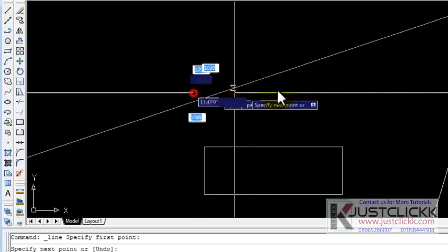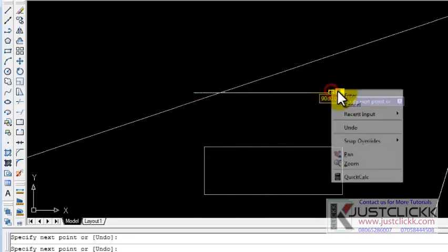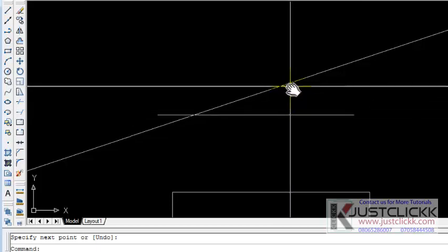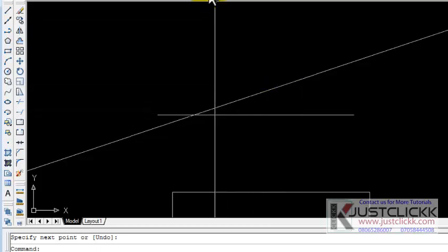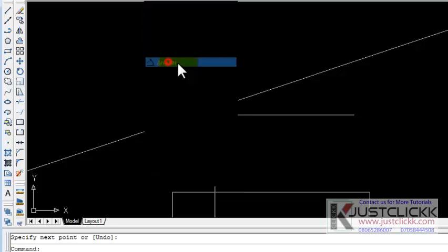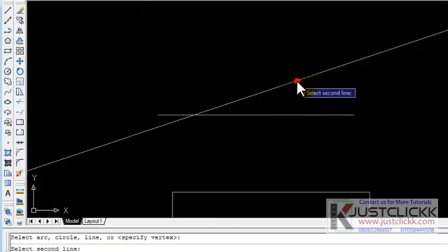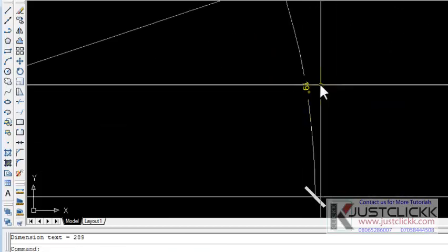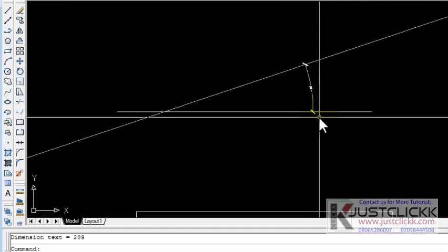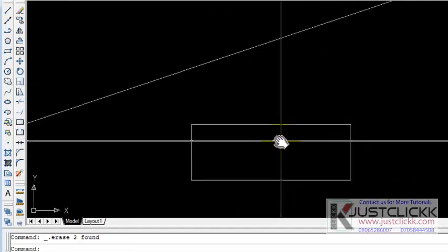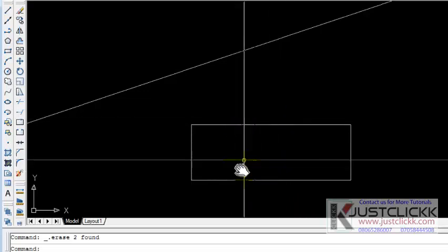So I will establish a horizontal line like this and then check the angle that deviates from that fence. So I will pick the dimension tool, pick the angular dimension, and then hit this point, hit the next point, and click. Let me zoom close, that gives me 19. So that means I have to rotate this building by 19.